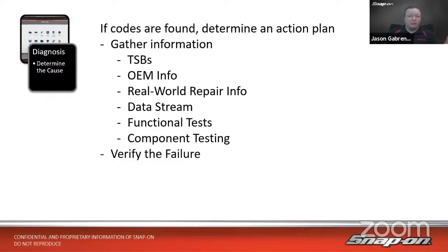How about real-world repair info? What have other technicians done in this same situation, right? Based on billions of repair orders in our case, that might be a good thing to have. Data stream, right? What is the computer trying to tell me? Because remember, the data stream off a computer is going to be the computer's interpretation of what it's seeing based on its inputs.